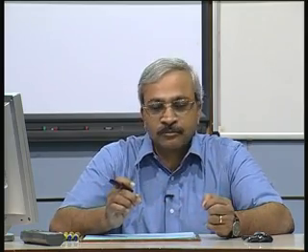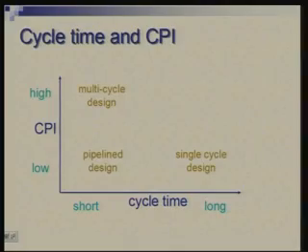The clock period, on the other hand, is still dictated by one operation and not the entire duration of the instruction. So, the cycle time would be more or less similar to what you get in multi-cycle design. There would be subtle differences, the two may not be exact. So, I am showing somewhat a qualitative picture and not a very quantitative picture.